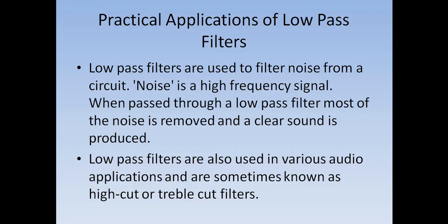Here are some practical applications of low pass filters. Low pass filters can filter noise from a circuit. Noise is a high frequency signal which happens due to different kinds of attenuation related problems. When passed through a low pass filter, most of the noise is removed. Low pass filters are also used in various audio applications and are sometimes known as high cut or treble cut filters.